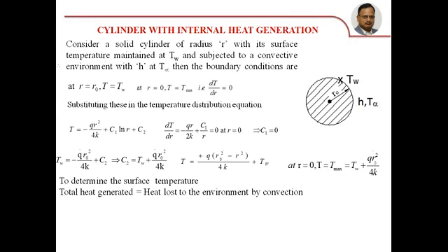These are all mathematical integration and substitution. Once you know the fundamental governing equation for the temperature distribution, you can solve it by applying the boundary conditions, and thereafter, if necessary, you can determine the heat transfer rate also. And to determine the surface temperature, TW, again we have to use the conservation principle.